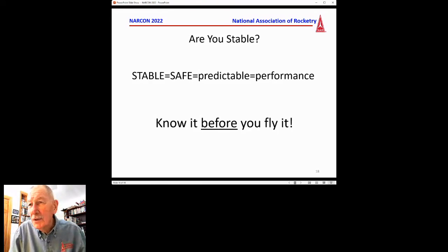For short rockets, you're probably more sensitive to that, but on the other hand, it's harder to move that center of pressure around because you don't have as much fin distance, although you can stick the fins out a lot further and what have you. I would say just use that same rule of thumb, and as long as you have that one diameter, you should be okay.